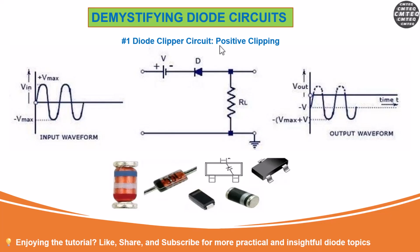So what exactly is a diode clipper circuit? Basically, a positive diode clipper circuit, as the one we've got here, removes or clips the positive portion of an input signal above a specific voltage level. The required components for this configuration are your voltage source in series with your diode, and a load resistor in parallel with this combination. Great. Now let's take a look at how this circuit functions.